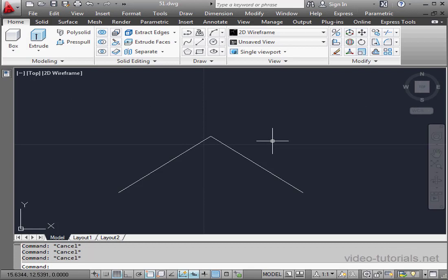Okay, in model space, I've got an example of G0 continuity. This is also known as positional continuity. You may hear it described this way too. G0 means that the ends of 2 curves or edges of 2 surfaces share a common position in space, but no tangency is present. What you end up with is a sharp angle or transition. There's a quick way to get rid of the sharp transition between these 2 lines here. You guessed it, we can apply a fillet. And when you apply a fillet, tangency is present.